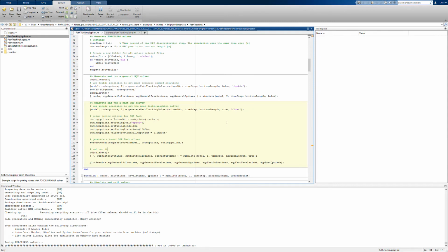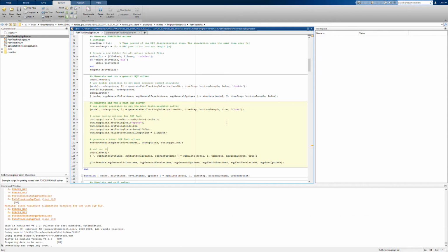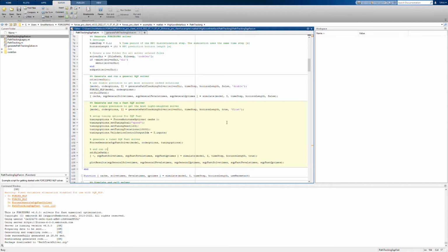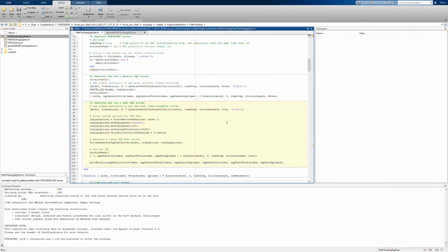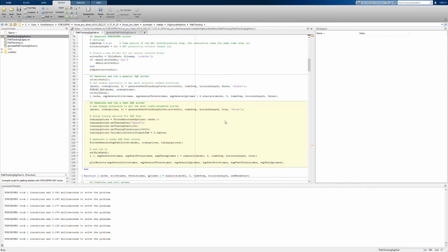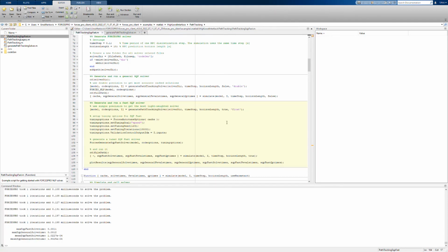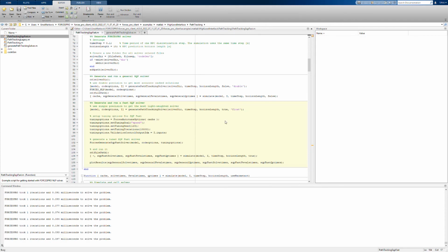The solver tuning is completed after 10,000 iterations, as set in the script, taking about 90 seconds on this PC, and the obtained tuning parameters are used for generating the custom SQP Fast solver. The new solver is successfully generated and downloaded to our host PC, upon which the new simulation starts. The simulation is now completed, and we collect and post-process the results.